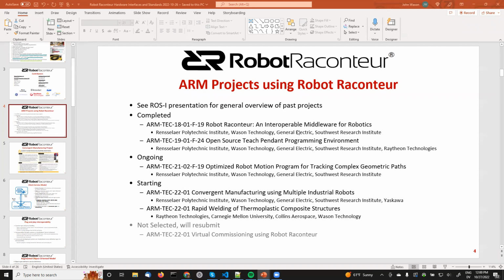The extensible messages are a good enough argument for me. Noted, and we've noticed obviously they're already kind of wobbling on the mandate that RMWs should be based on DDS. I think for some of these things, right? Like Zenoh or something is proposing an RMW, and somebody as a joke made an RMW on email, right? And OPC has talked about creating an RMW implementation. So we're already seeing some wobbling on the DDS side, because to your point, this whole notion of how you manage the semantics and extending messages just sits on top of DDS, right? And DDS just ends up being the transport layer, in which case you can use about anything for transport. So, is it really the right solution if you end up having to do all this other stuff to get it to work? I think it's a worthwhile thing to think about.